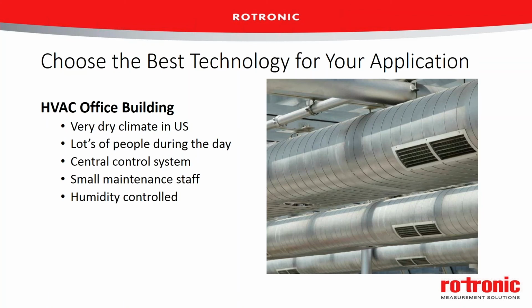We're running off a central control system, so we probably want to get some feedback back to that system. We have a relatively small maintenance staff, so we need whatever sensing system we've got to be low maintenance. And we know we're humidity controlled. So probably what we're looking at here in this application, we probably also have a fairly limited budget. We're in a dry system, so we don't really want the resistive sensors. Mechanical sensors aren't going to be able to send information back to a central control system typically. Those you're just going to read directly.